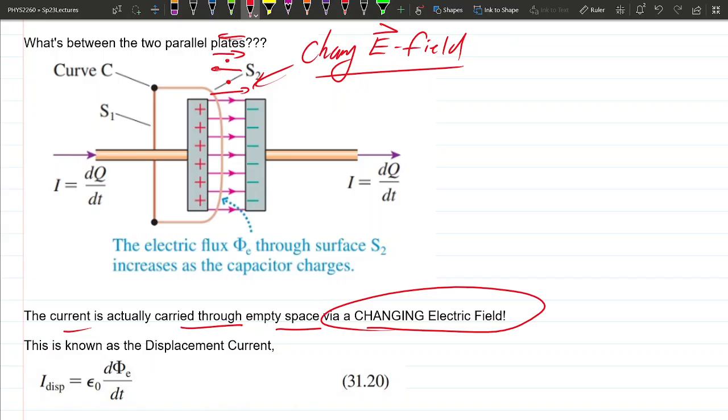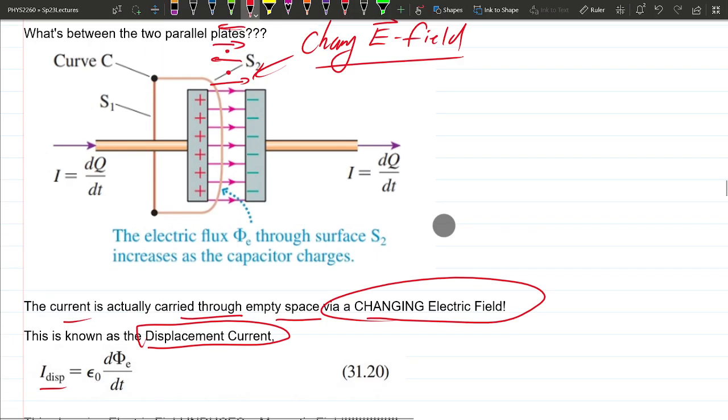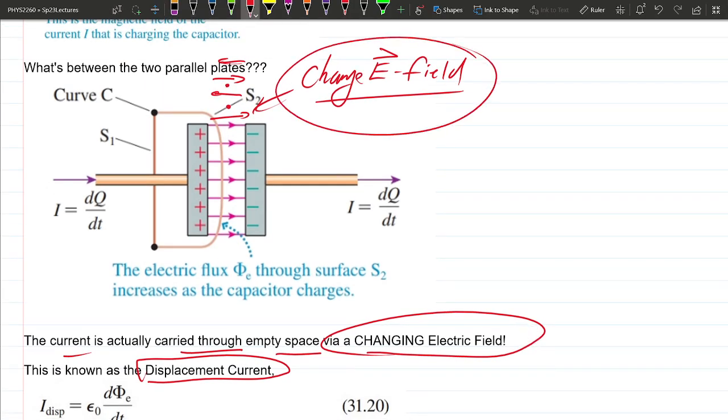And then what happens is that when the voltage flips, the positive charge lines up here, the negative charge lines up here, and the changing electric field is what's transferring the current over. Okay, so this is not a real electron-moving-around current, so we're going to call that displacement current. It's a special name. It's not technically charges moving, but essentially it transfers that energy over the capacitor just the same. Okay, and this displacement current, as we saw up here, has something to do with changing electric fields.